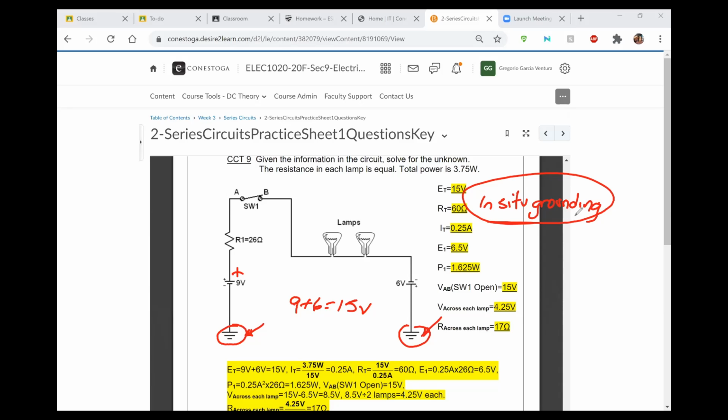It just means that from your panel, you have your water pipe, your water meter. So you are going to be sending a number 6 conductor straight into that pipe. When you send it to the water pipe, which is a metal pipe, this wire is called a grounding conductor, a grounding wire.